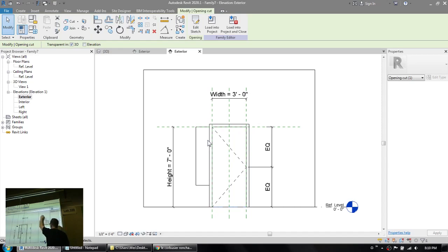And there will already be a center line reference plane going down the middle of the window, which would deal with this divider up on the window. And maybe another reference plane here just to catch that little decorative divider between those windows. So, you know, wherever you've got a major division of your family, you put a reference plane there. So that's your first order of business.